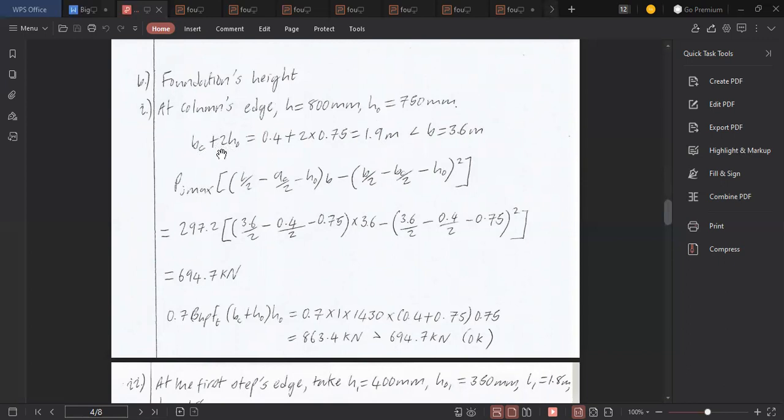So BC plus 2H0 should meet the requirement that BC is the breadth of the column. Wait, finding the effective depth, the protective cover, that's the one that's subtractive, right? Is there a range for it? Maybe 40, say, between 35 and 60. I think that's where I've seen most values from. Yes, between 35 and 60, something like that.